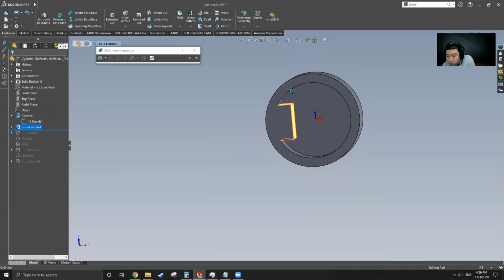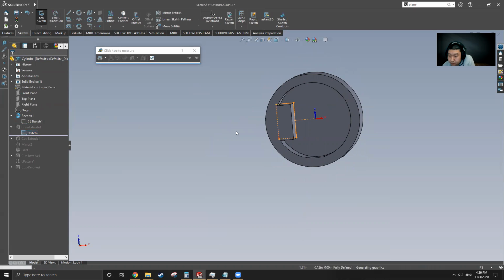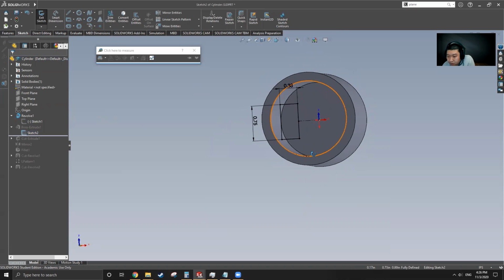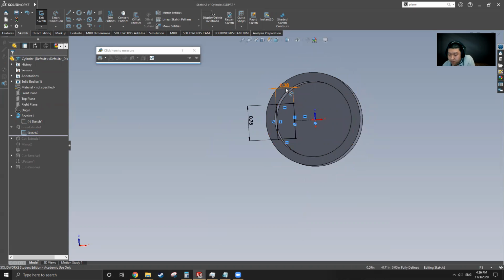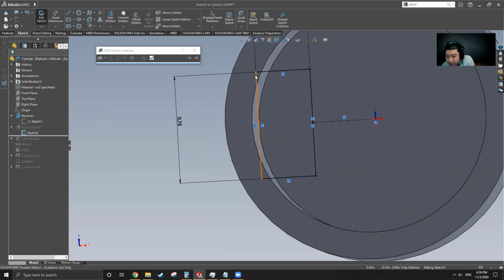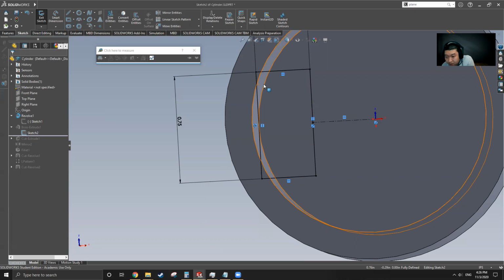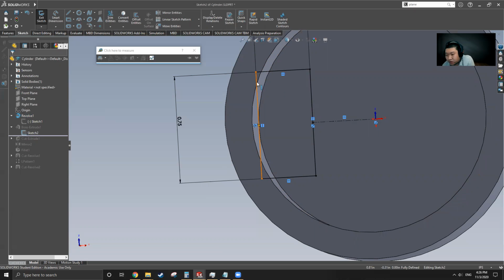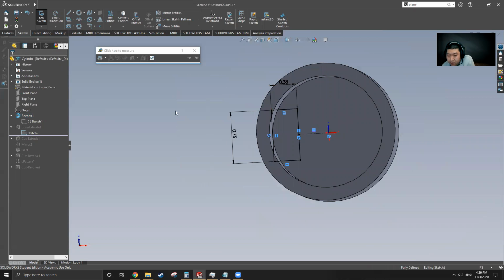So there will be one extrusion made inside of this cup. And the dimension is 0.38 and 3/4. And pay attention, this edge is going to be tangent to the ID of this cup. All right, so this circle I'm highlighting right now is going to be tangent with the left edge of this extrusion. Okay, so 0.38 and 3/4.